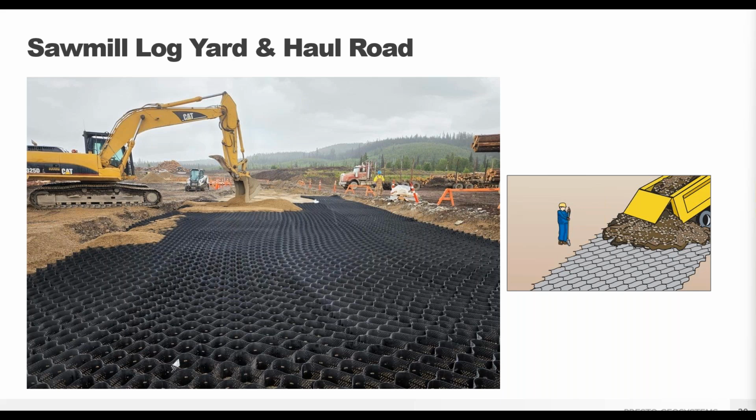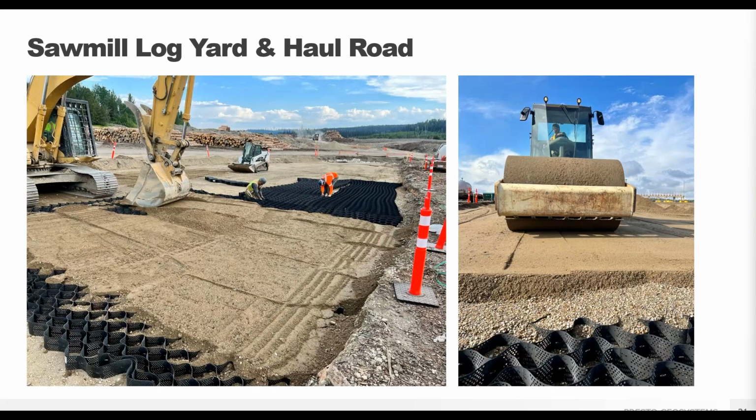Here we see the infill being placed, and a good technique is to limit the drop height to 1 meter or less, about 3 feet, to ensure the empty geocells don't fold over and that they're evenly filled. GeoWeb created a smooth platform that eliminated the rutting and constant maintenance, and both project owners and installers were pleased by the ease and speed of installation thanks to the AtraKey connectors.